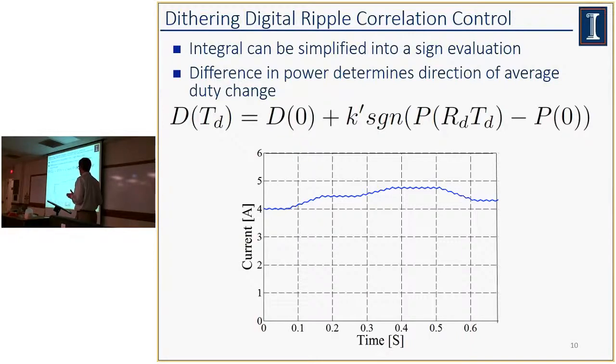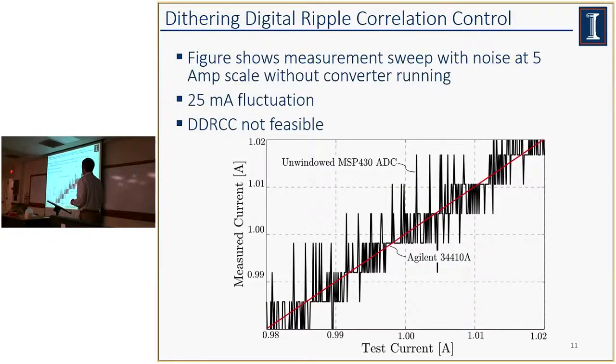So just to reiterate that, basically as the panel current changes from 0 to the maximum power of the panel, that all has to fit into the 0 to 2.5 volt range of the ADC. So our input amplifiers will scale this all into that 2.5 volts. Now that sounds nice until you realize what actually happens in a low-cost microcontroller when you're sampling.